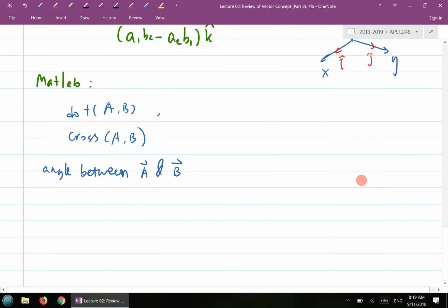So, here's one method I typically use, which works well for all different kinds of situations. If you want, you can try it out yourself. I use a function called ATAN2 to calculate this angle. Within this function, we use a command called norm. Norm calculates the length.